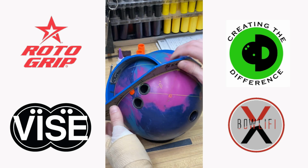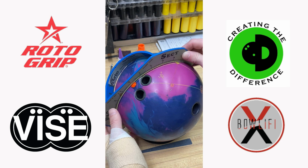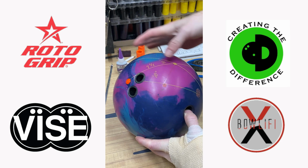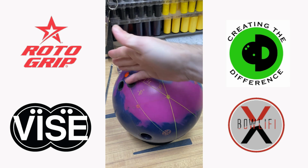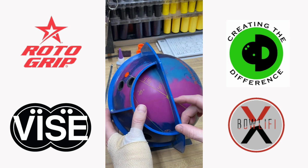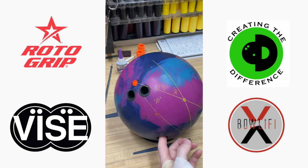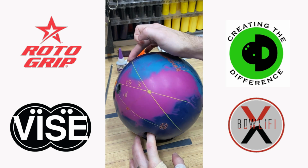The next thing we're going to do is figure out a pin to positive axis point distance. So in this case, we're right about 4.5, give or take. So that's what the distance from here to here is. And finally, the last angle is between the pin to positive axis point line and the VAL. In this case, do the same type of thing, and you'll notice I've got this right about 40 degrees. So those are the three numbers: angle 1, pin to PAP distance, angle 2.